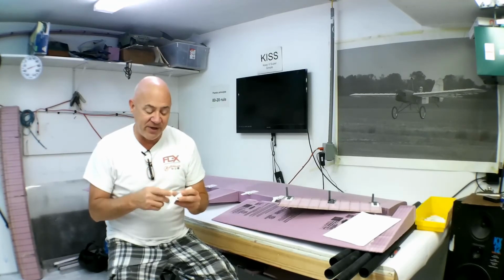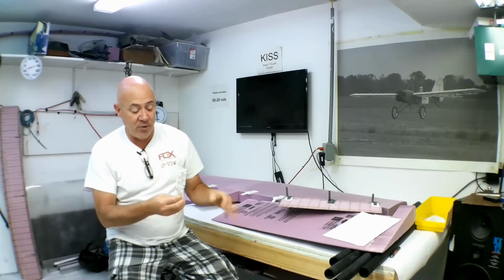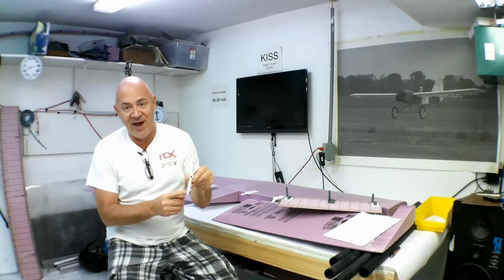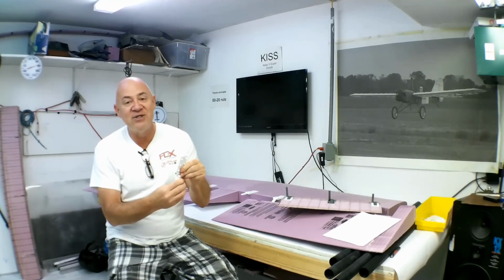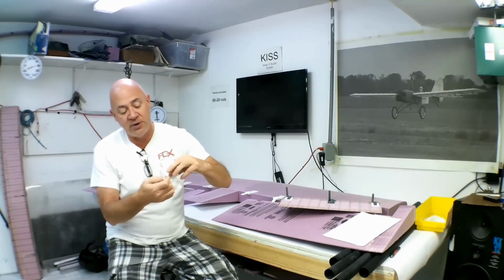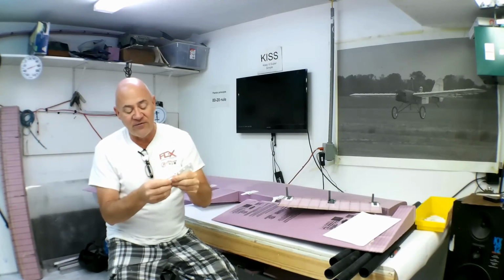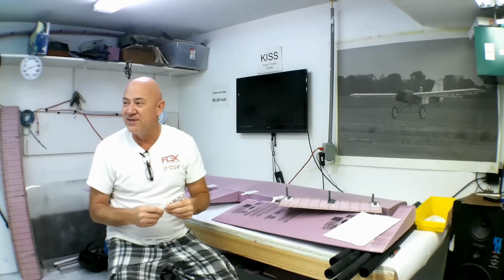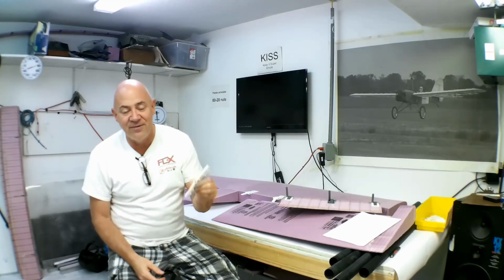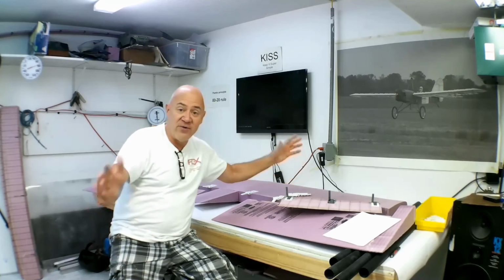I know how to design in 3D. So when I took this hinge right here and mounted it to a table, I was able to put 165 pounds on this before the hinge started to pull apart. It didn't break. It was starting to turn the 440 screw sideways out of the ABS. I need to look at the numbers, I might have been at 178 pounds and 4 ounces or something like that. But it was insane. This hinge will pull out of the foam and fiberglass and everything way before this hinge will fail. Okay? So that's all I want to do in this video, everybody.